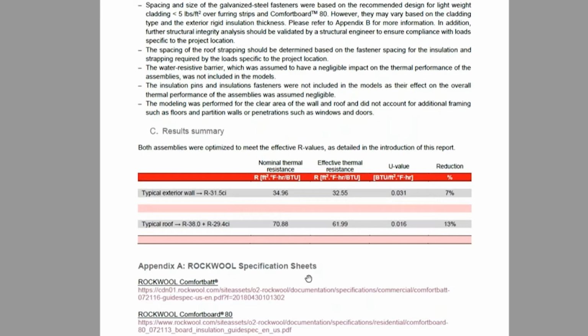It's a great idea to consider hydrothermal analysis to validate the moisture drive in your assemblies and make sure that the changes or the thickness of the interior insulation are not going to lead to some serious problems, especially when it comes to moisture. And it's recommended when you do a renovation.